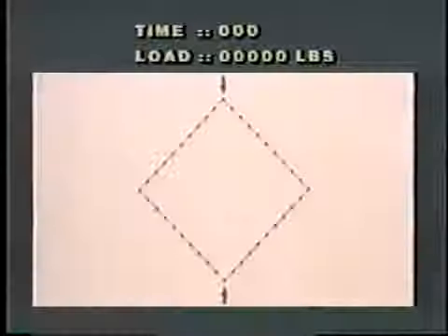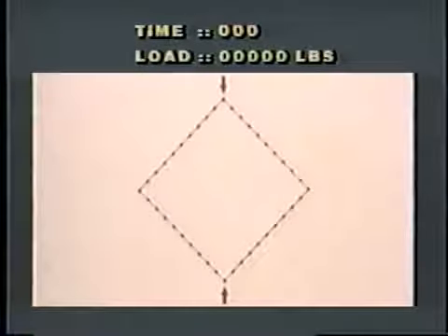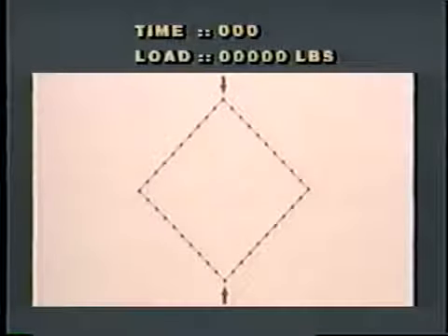The second animation shows a frame that is subjected to forces such that the frame undergoes very large displacements. Here we see the frame modeled using beam elements that we discuss later in the course. The frame is loaded as shown by the force arrows. There are pin connections at the points of load application. The frame is assumed to be of an elastic material, hence no plasticity is assumed to develop, although the frame will be subjected to very large displacements. The indicated loads will push the top of the frame down and the bottom up to such an extent that the points of load application cross over.